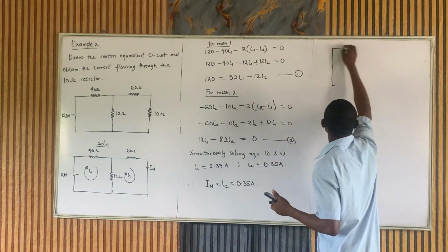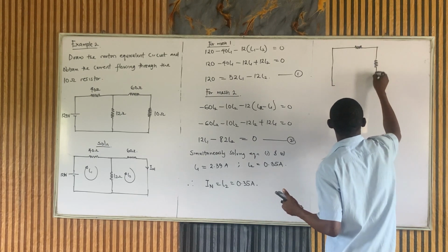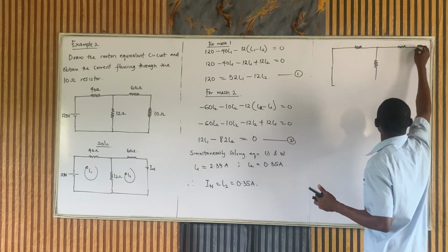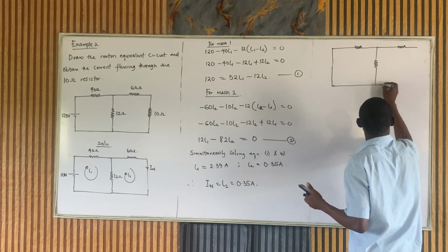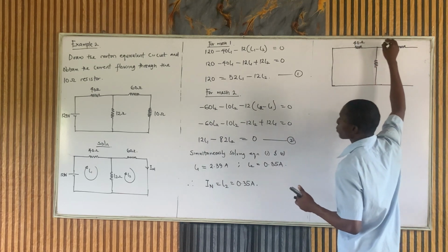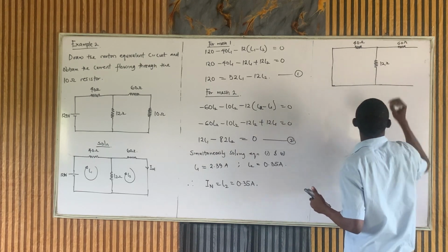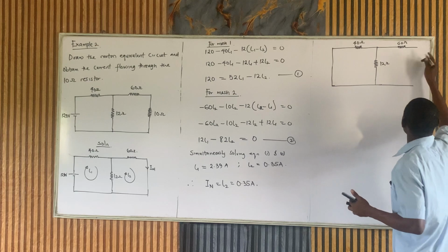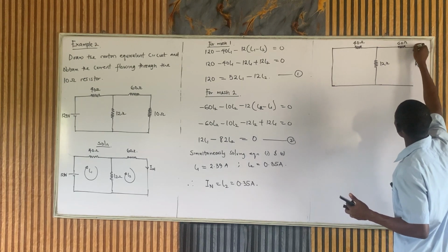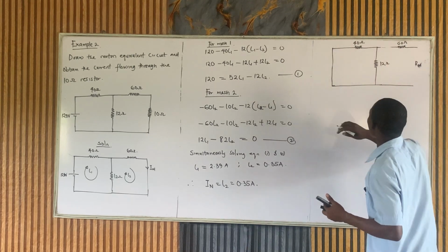So we're doing that right away. 40 ohms, 60 ohms, and 12 ohms. Okay, like I said now, I'm looking for the RTH here, RN here, sorry. So assume current is coming from it. That's what I used to assume. To get here and split, some will go here, some will go here. These two parts are in parallel.